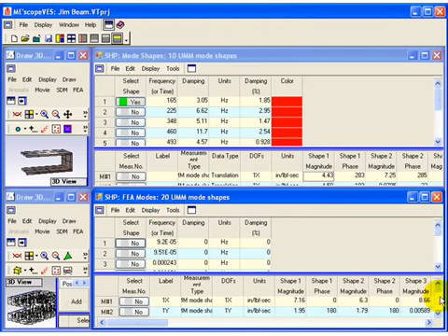Notice that the FEA mode shapes have 630 degrees of freedom, 315 translational DOFs, and 315 rotational DOFs. Only the translational DOFs will be displayed in animation and compared with EMA mode shape components at matching DOFs. Notice also that the first 6 modes have very low frequencies. These are rigid body modes.